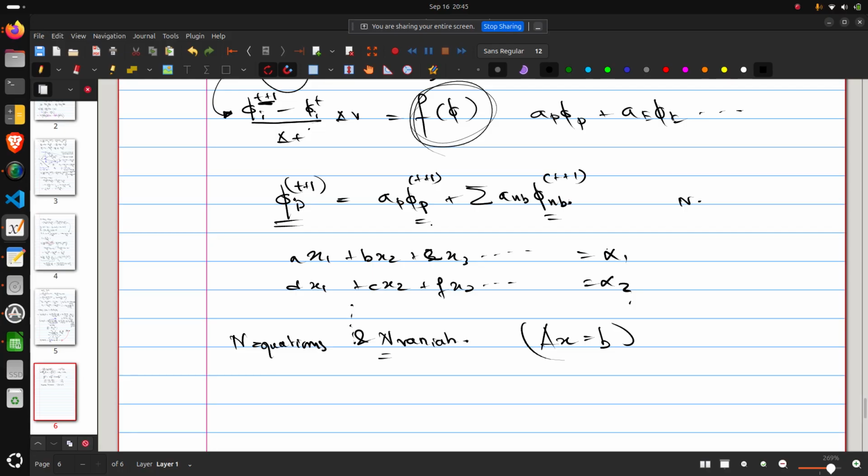So the concept is that when you are doing a temporally varying system or an unsteady problem, if you end up with a system of linear equations, that is, you are using the values of the neighboring cells and the cells at the current point of the same time step, that is, all of these are unknown, this will result in an implicit solve, right?